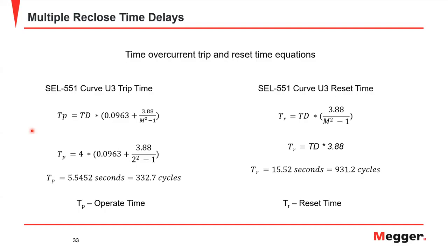Fortunately, today, microprocessor relays can be coordinated, whether downstream or upstream, with other microprocessor relays and with electromechanical relays. Now, electromechanical relays have a feature, which is that they trip on one curve and they return or drop out on another. And that is something that can make it a little bit challenging to coordinate. So it's better to use, and the ability that we have today, a computer program to do the coordination rather than relying on hard and fast rules of use this many cycles and things like that.